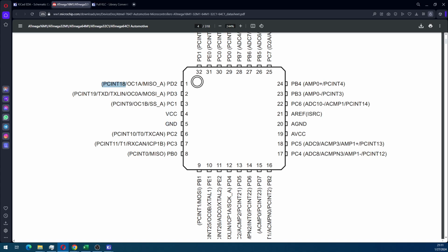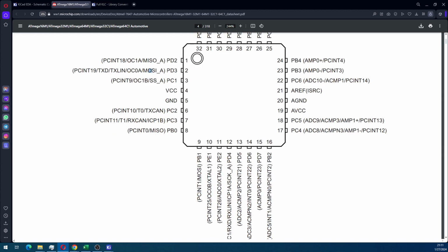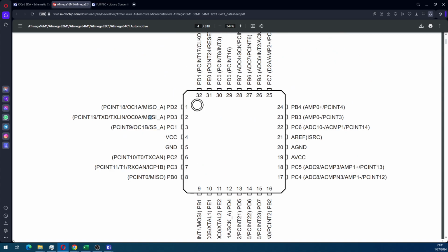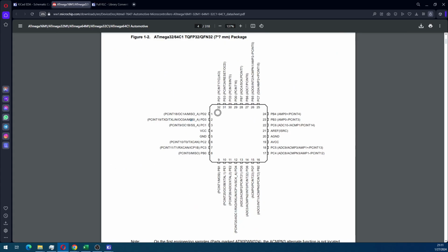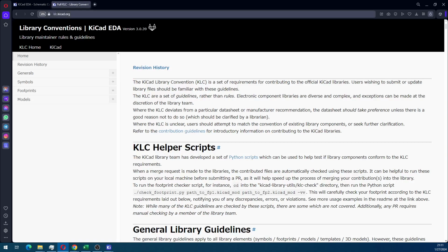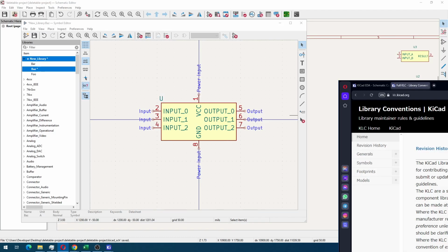So you've got, for example, a pin change interrupt, a timer counter function, a serial interface, and you can really put too much text on the screen if you try to encode all of that at once. So sometimes it's convenient to be able to just right-click your part and tell it which pin alternative you want to select.